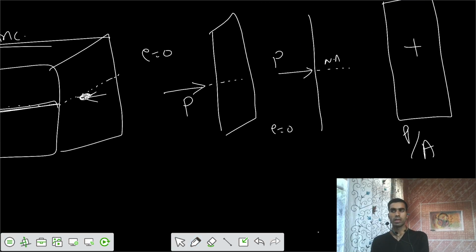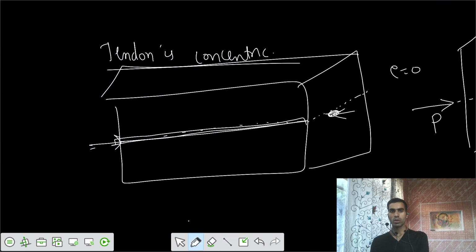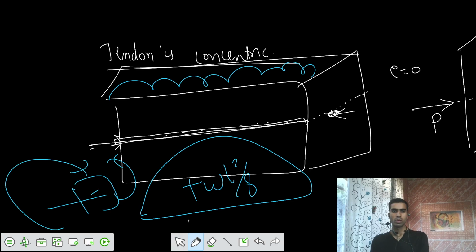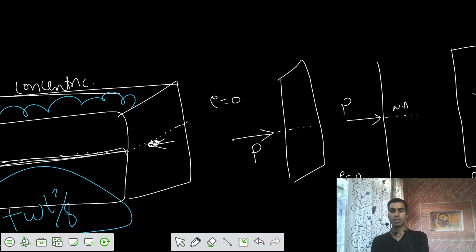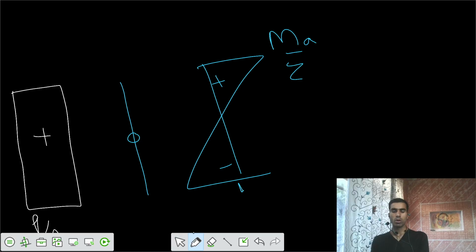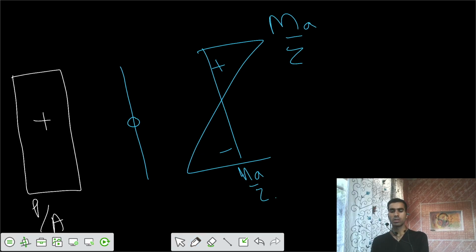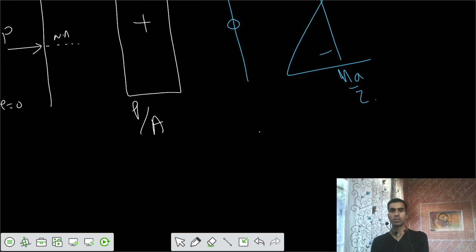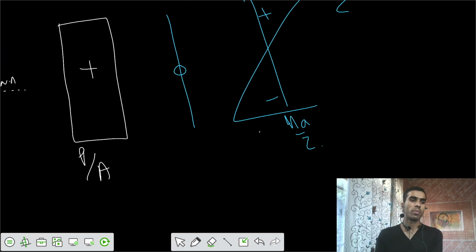Now if I talk about the external moments, because there was some dead load and some live load, it has provided you a sagging bending moment of WL square by 8. That's positive, so top compressive, bottom tensile. So top M all by Z and bottom M all by Z for the symmetric section. We are calculating in terms of section modulus. Your section modulus on the top side is also the same as that of the section modulus on the bottom side.